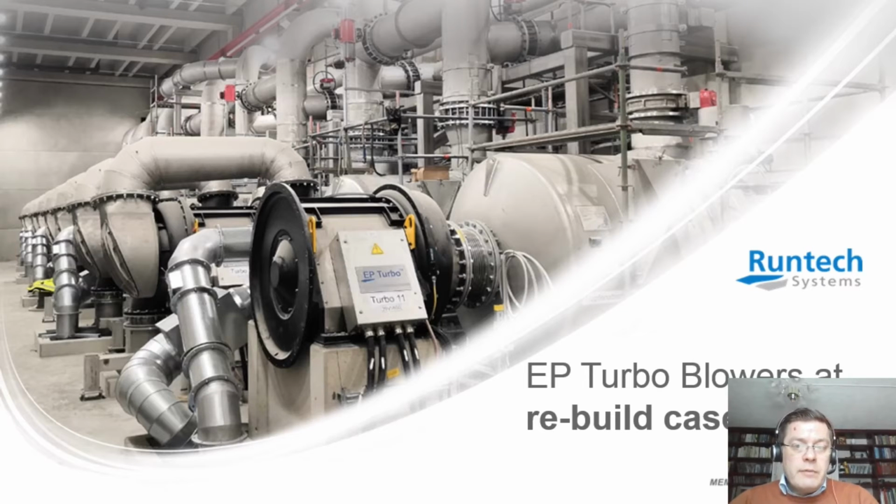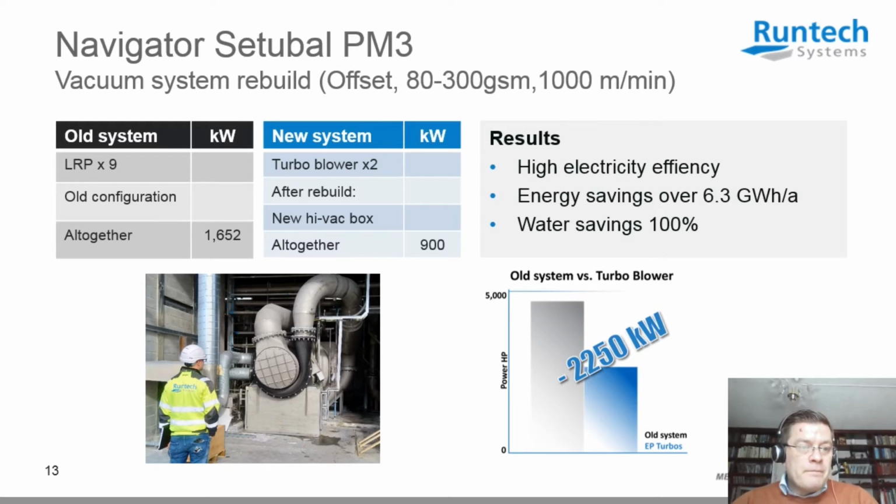Then a couple of rebuild cases. Full vacuum system rebuilt in Portugal. 9 old liquid ring pumps replaced with 2 turbo blowers. The 2 turbo blower system and EcoFlows were done in 2 steps. No need for a long maintenance shutdown, but all of the works could be done during normal production. Turbo start was also made one by one. Savings 45% in electricity and 100% in water.